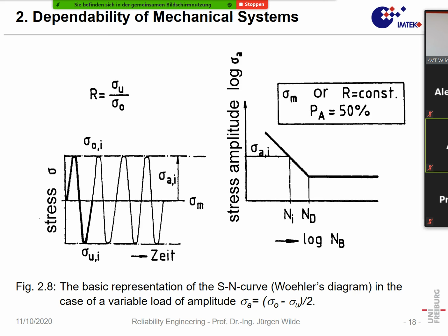That's, for instance, the trick in high-strength glass we used in facades or so. This glass is hardened in a way that on the surface we have always compressive stress, and as cracks always start from the surface, all cracks which could be there are always closed by the compressive stress. And that means the survival probability will be very high.